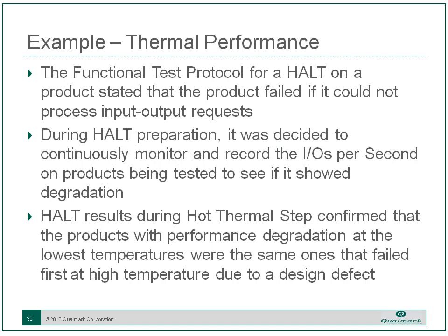And here's an example of a use of a key performance indicator. We were doing tests for a customer on a product, and the functional test protocol stated that one of the failure modes was if it could not process input-output requests. However, we were able to monitor during HALT the inputs and outputs per second that it was processing and see if there was a degradation in it.